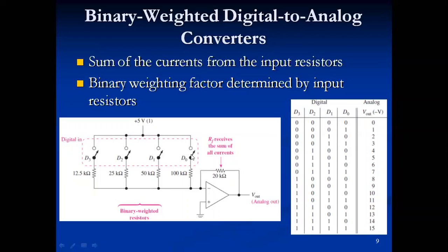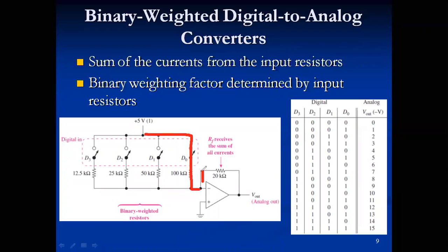Do the math really quickly. I need you to see that there is, I'm going to annotate this. Is it 0.05 milliamps? Okay. Does anybody agree with that value? We're going to look at this path. There's no other current path. So we have 100 kilo ohms in series with the 20 kilo ohms.